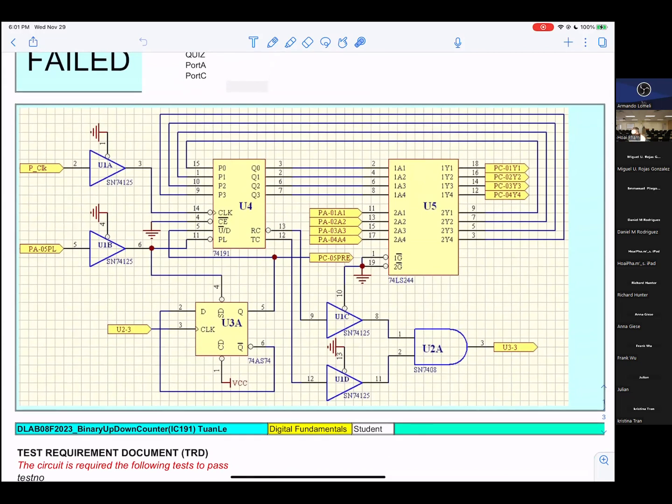And now U1 or U2, they are already routed for control. That means they are enabled all the time. You get a 0 in, you get a 0 out. You get a 1 in, 1 out. Nothing else. However, the only difference is sometimes you get 2.5 volt input, okay, and the output is supposed to also be at logic high, but it can bring up to 3.2 volt. Still logic 1, but you want the logic 1 close to 5 volt as much as we can, okay? So that's why they're using the buffer, just to bring the output to the standard logic state, okay?